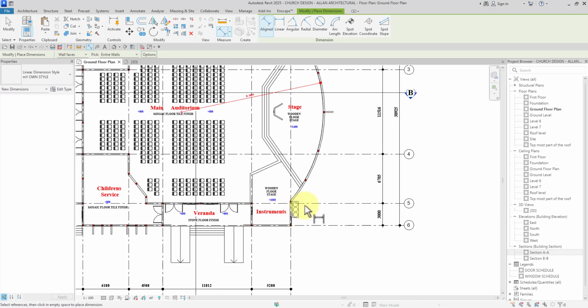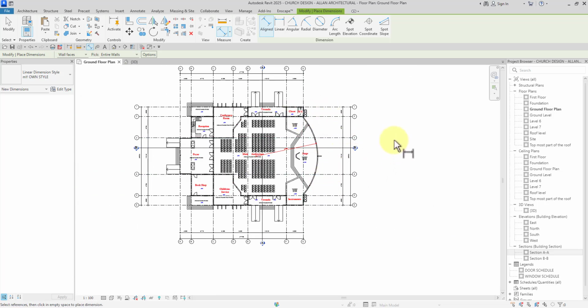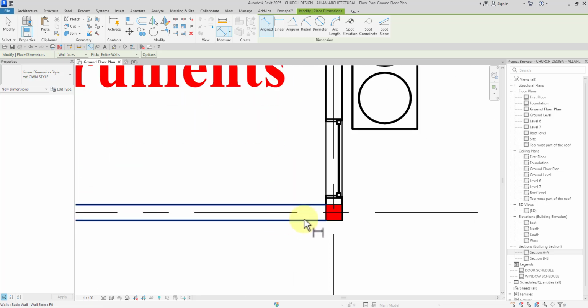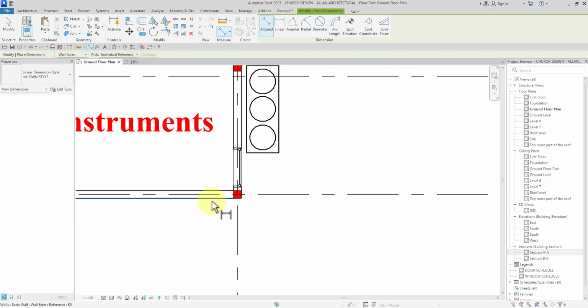And with our next dimension, I explained in the previous working drawing series, we are just going to pick the openings of that face. All right, so everything facing this direction on the wall is what we are going to pick the dimension onto our grid face right here. So we are going to click on the surface of the wall right there. So make sure wall faces is selected. This is perfect. And individual references.